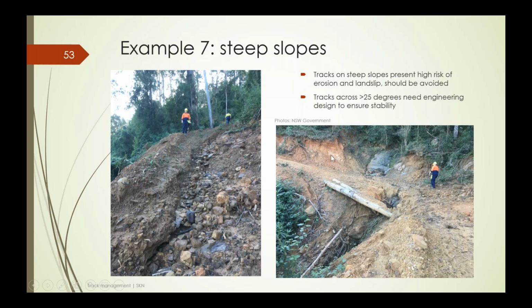Steep slopes. Look, really, this just reinforces the fact that if you are putting in a road on steep slopes, it's going to be a major operation. It requires a lot of planning. On slopes this steep, obviously well over 25 degrees, it needs geotechnical design, and it's going to be expensive.